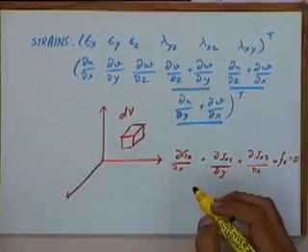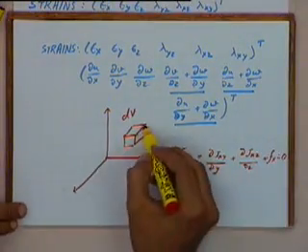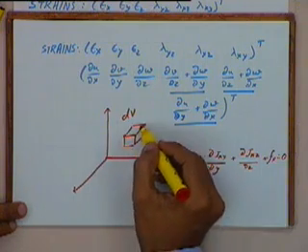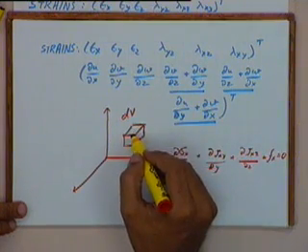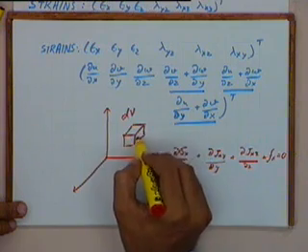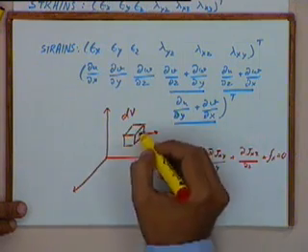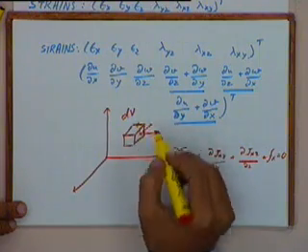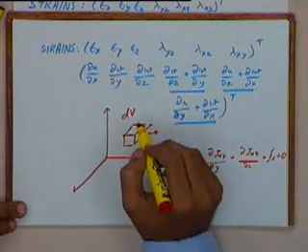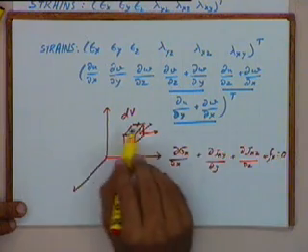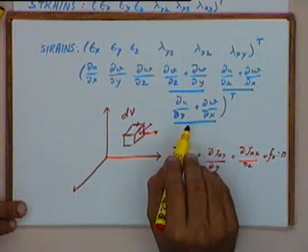This you must have done in your solid mechanics. You take this elemental volume and find the forces acting on all the faces. For instance, because of the stress sigma x, there will be force acting in this direction. Because of shear forces, there will be force acting in these directions, and so on for all the faces. Plus, there will be an elemental body force.